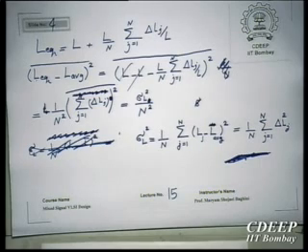If you have a transistor with a width of W star and L equal to L, and I make n parallel transistors, the standard deviation of effective L will be less than the standard deviation of L of a single strip. That is the whole point.